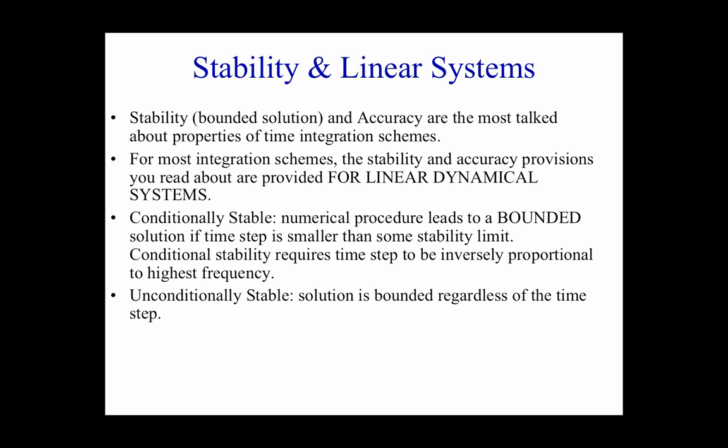So a conditionally stable one means that it's basically a bounded solution if the time step is smaller than a certain time step. And unconditionally stable is kind of the methods we like, in that we can use any time step, and for an elastic system, we're going to have a stable solution, i.e. the solution is not going to grow.